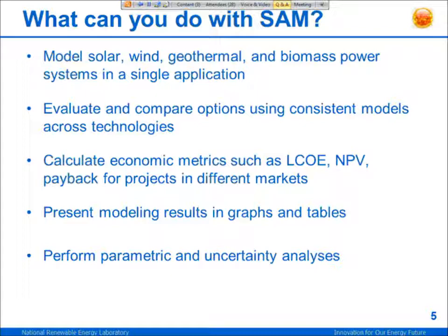SAM calculates economic metrics like LCOE, levelized cost of energy, net present value, and payback for projects in different markets. It calculates a bunch of results, which it displays in graphs and tables that we'll see. And then it also allows you to do some more advanced analyses like parametric and uncertainty analyses.